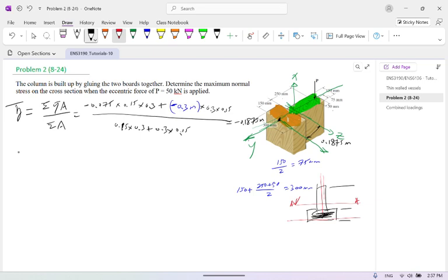So of course we still should work on the I, because the structure. So I remember this IC plus AD square because of parallel axis. So any structures here, you can see this structure. This one is B, this is H. Okay, this is X, this is Y. So then of course you can see Ix is equal to 1 over 12 BH cubed. So please don't forget this, it's a basic thing. So of course from here, we can work on IZ direction, neutral axis, equal to the summation of all the IC plus AD square. Okay, you can work out.